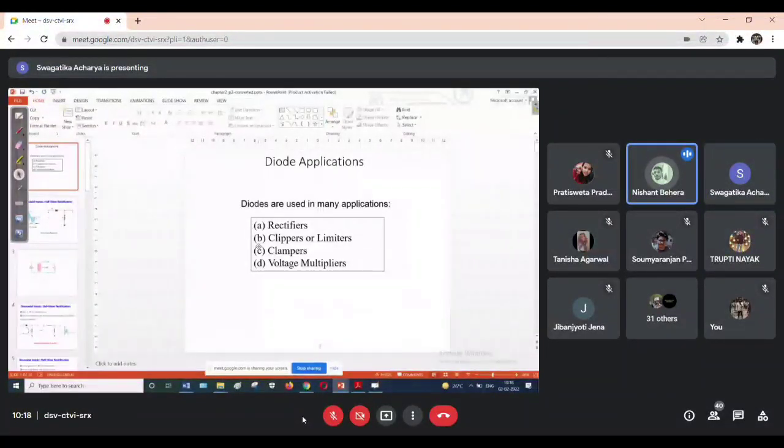Ma'am, it basically rectifies the signals, I mean, the waveforms. It rectifies the AC to DC. In general layman language, you can say it converts AC to DC, but the basic correct thing you can write is that it is a device which converts a sinusoidal waveform having 0 average value to a unidirectional waveform, or you can say DC waveform, with a non-zero value. So I can say this is a rectifier.